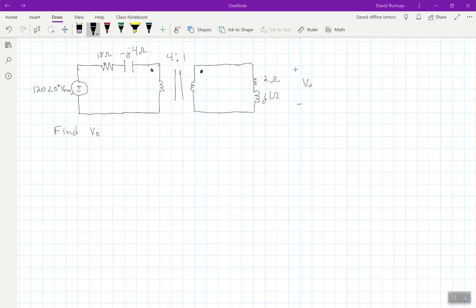Just like conversely, if you have an inductive line impedance, you often want to have a capacitive load. And that comes from maximum power transfer. Remember, these capacitors and inductors give us that Q, those volt-amp reactive power. And we want to cancel that out as much as possible for maximum power transfer. And so, if we have capacitive on the input, we would want inductive on the output.